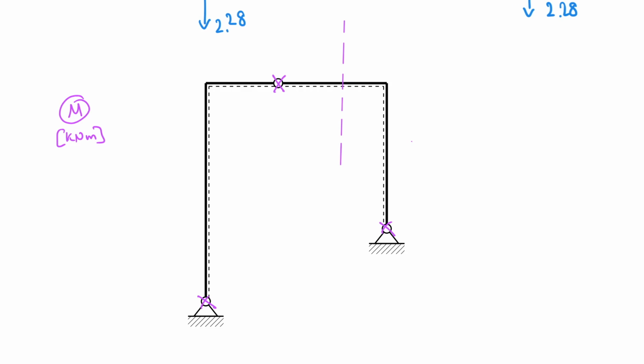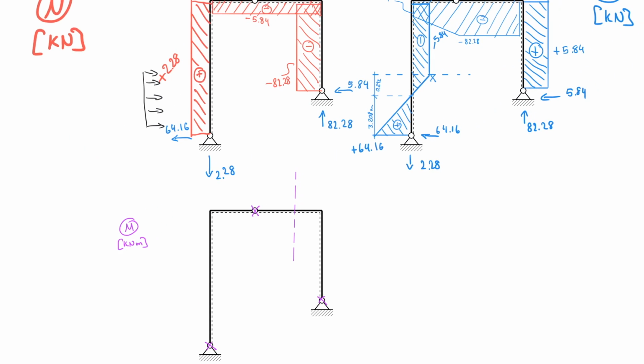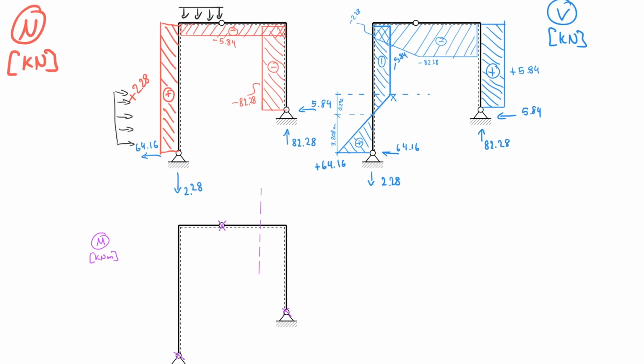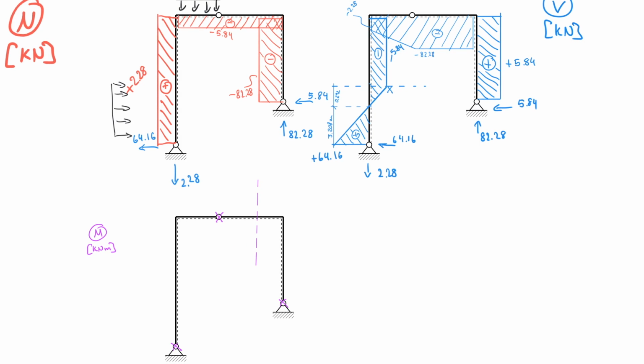When I go through those drawings, I know where it's linear and where it's not linear and where it's parabolic and so forth. So it always helps to look at the shear force diagram at the same time. And let's start at the bottom part. So here we know we have a positive slope, negative slope. So that means that my parabolic function must go like this.